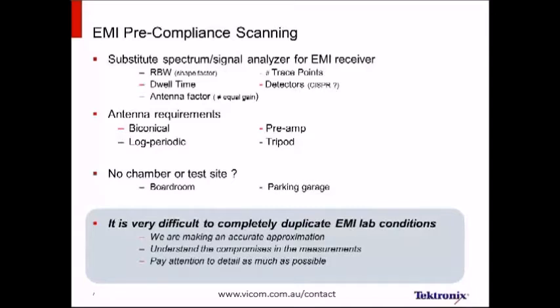People are often a little bit confused about this particular situation because if you didn't have an anechoic chamber, are the measurements valid? And the short answer is yes. We may have to use a boardroom. We may be able to do it in our lab if the lab is RF quiet enough. Or I've even seen people make measurements in a parking garage. Ultimately, it's very difficult to duplicate exactly what the EMI test setup is in the test house. We can make a very accurate approximation, but it's not the same. We need to understand the compromises in using a signal analyzer versus an EMI receiver, and we have to pay attention to as much detail as possible.